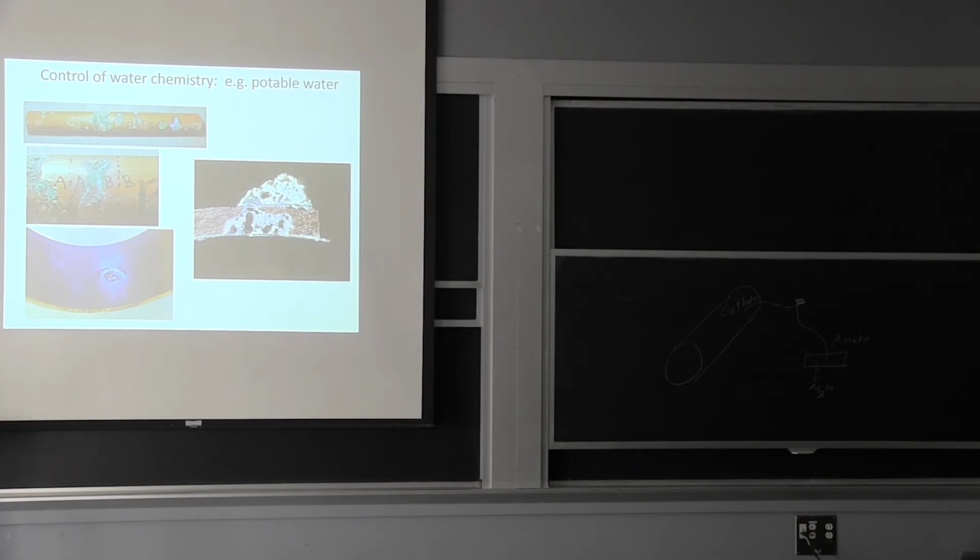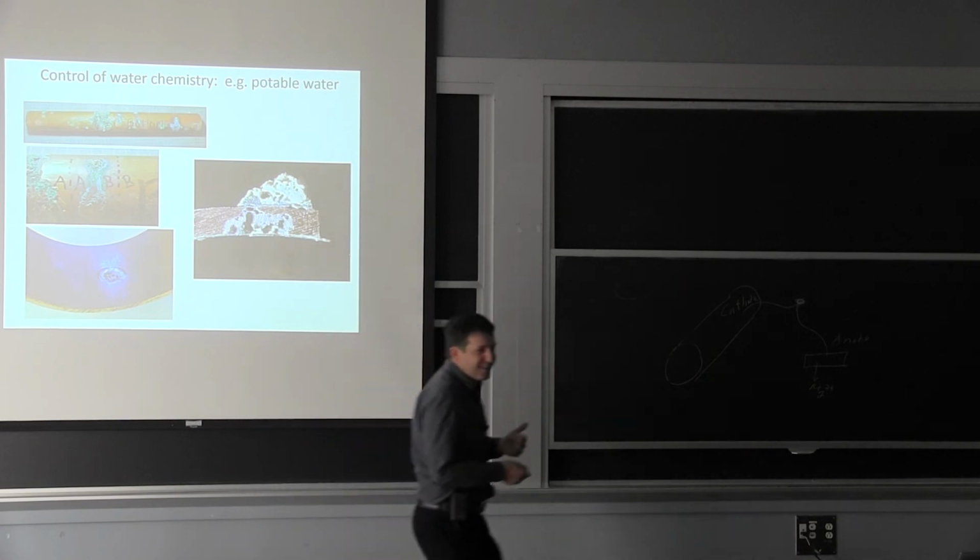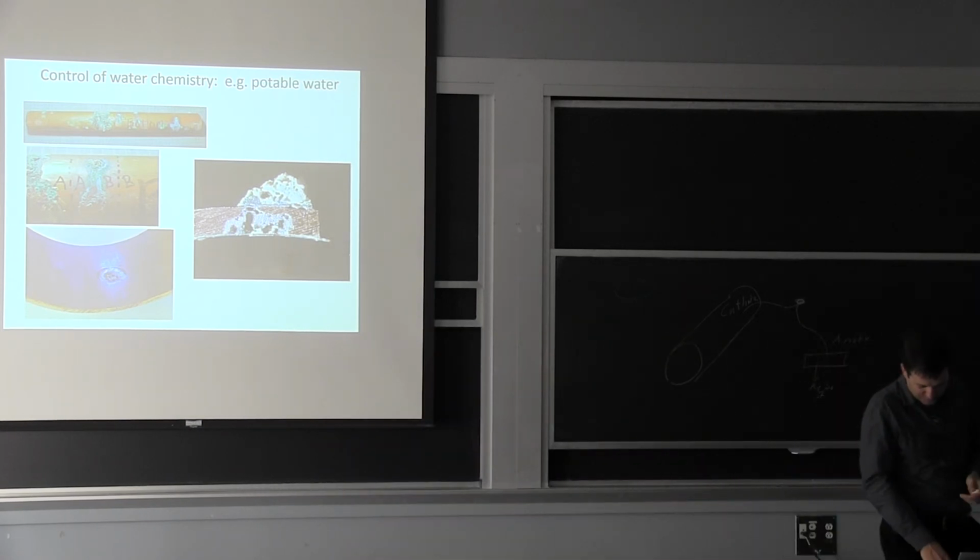So it's not necessarily the most safe system, but I've seen it work in a number of systems. And then eventually you get too much of it, and it will leak. If you're at a location where there's thermal expansion and movement of the pipe, you can't really build up on the outside like here, and then you get a leak at those locations. So I think it's a scary example of practical crevice corrosion.